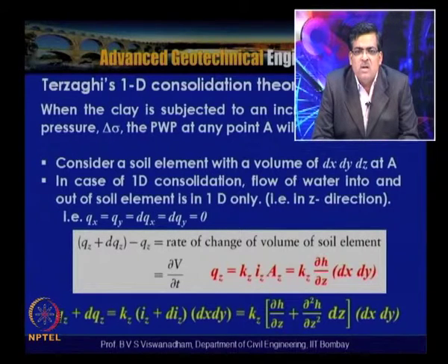If you have a finite area which is loaded, there is a possibility that three-dimensional flow can happen in the y direction, the x direction, as well as the z direction. But in the case of large area loadings, one-dimensional consolidation is possible.